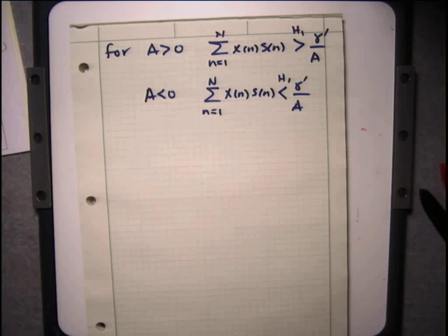Okay? So the bottom line here is, for this particular problem, if you did the GLRT without knowing anything about the sign of A, you couldn't say anything about its optimality. However, if I told you A is not known, but I know that it's positive, then what you have is a so-called one-sided test. It means I know that the parameter has to be to the left or to the right of 0, or to the left or right of some fixed value. Then I could come up with an estimator that in fact will give me a uniformly most powerful test.